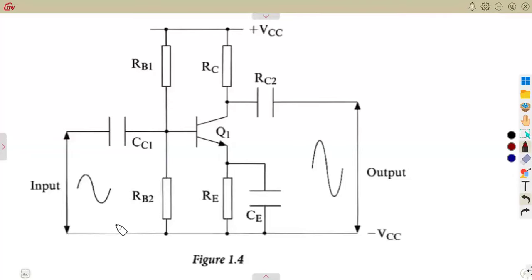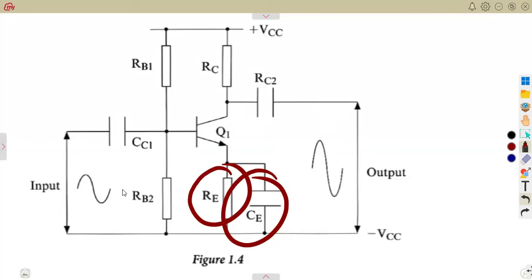So as we talk of the voltage divider bias common emitter amplifier, we are going to notice that this is simply one and the same as what we had before, working with the fixed bias common emitter amplifier that had the emitter resistance and the emitter bypass capacitor. Remember, we talked about this when this resistor was not involved. We're just considering our RB and our RC.